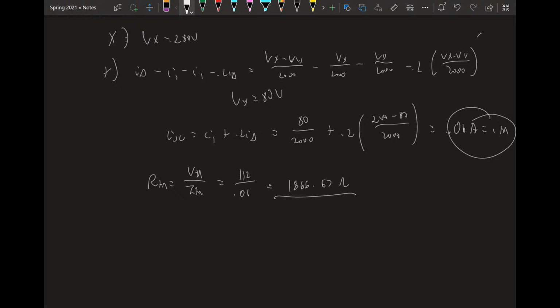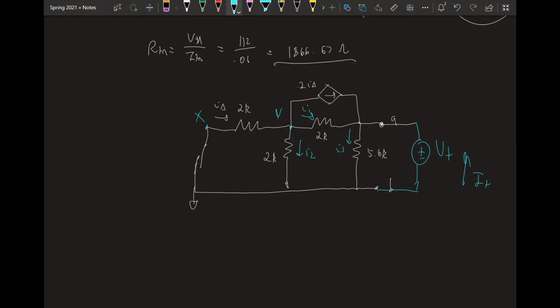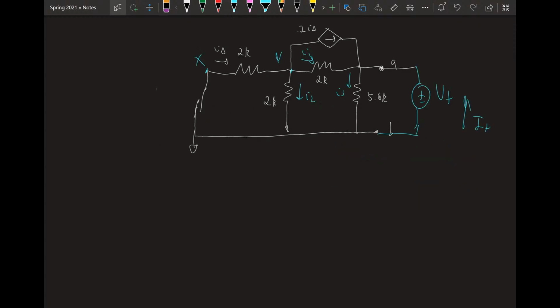Once again, I'll turn to the power of node voltage because that's what I tend to use. So let's solve. Vx at node X is grounded for this scenario, 0 volts, right? Vy, once again, same system equations. I delta, I'm not going to write out this time. I delta is now 0 minus Vy over 2000.